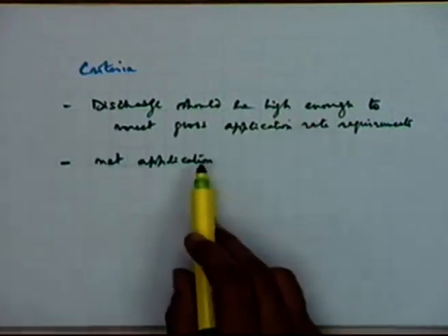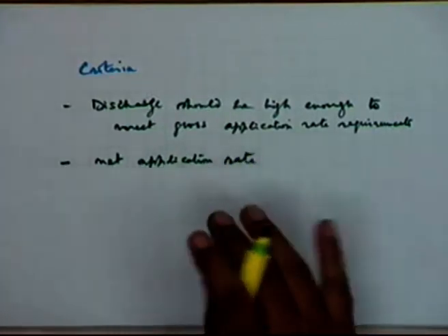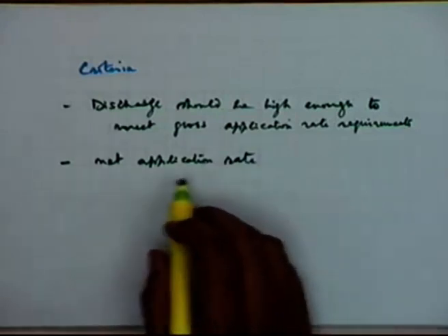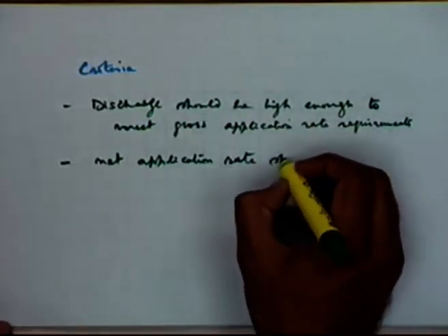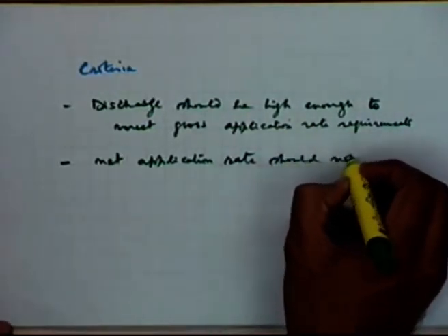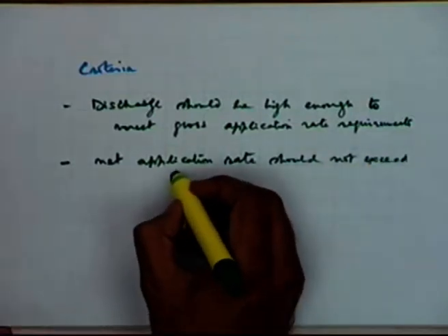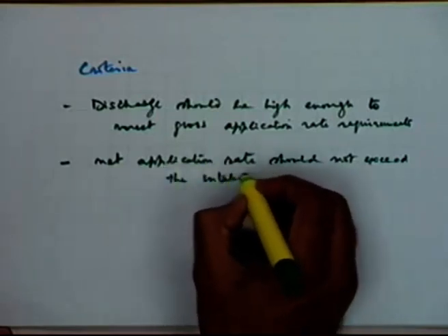But when you come to the other side, the net application rate, you have a criterion which is just diagonally opposite. The net application rate should not exceed the intake rate of the soil.